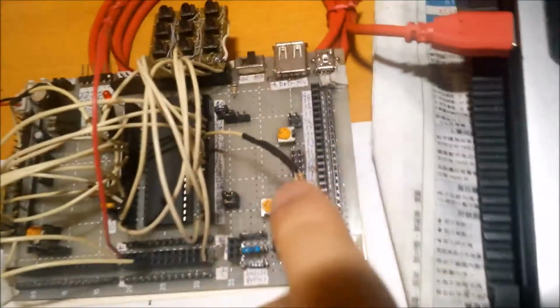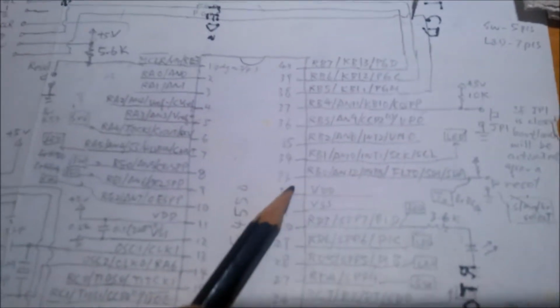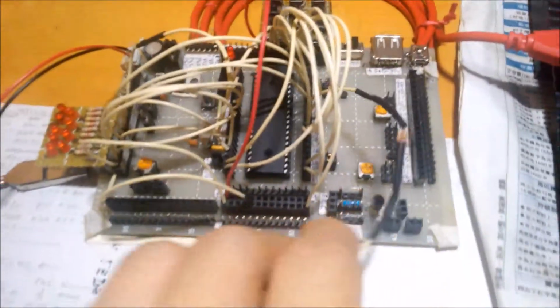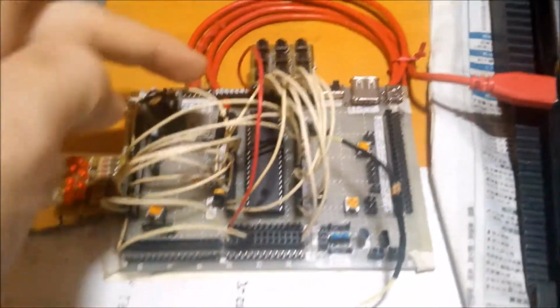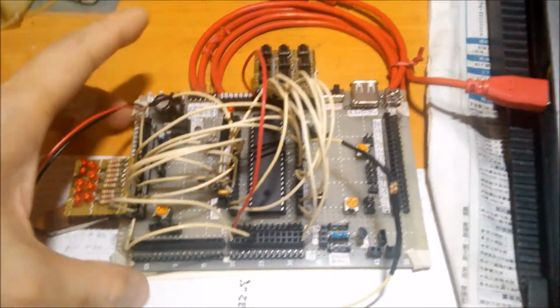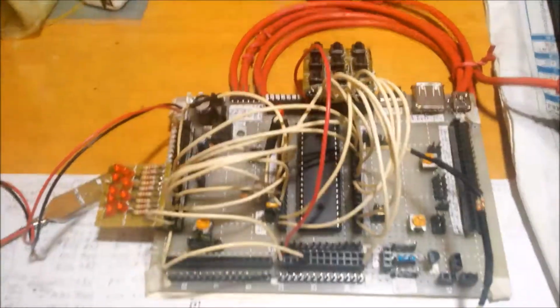And also a lead wire here. This is also for testing. It is attached to interrupt 0. This is the pin, let's see, it's INT0 here, number 33. And now we test it by attaching it to the 0 volt and see if this LED flips or flashes, and it demonstrates the interrupt subroutine is running.